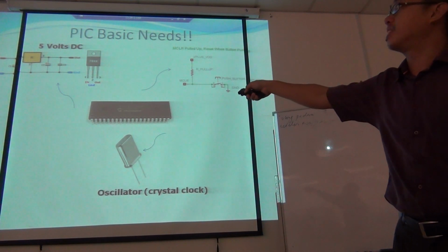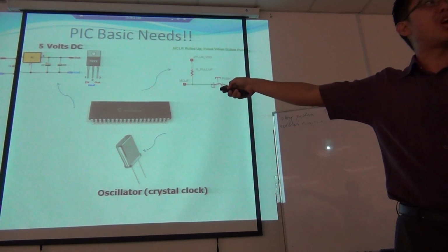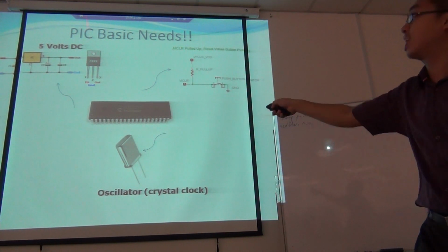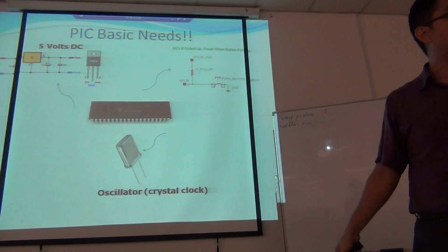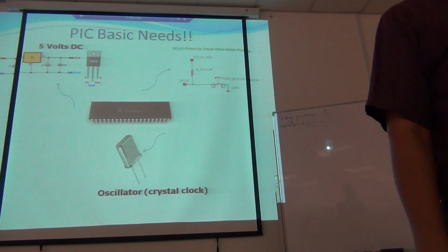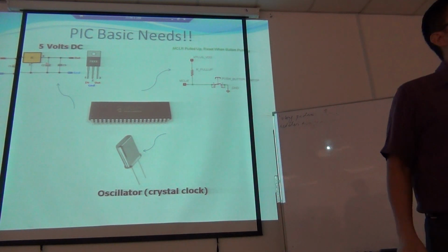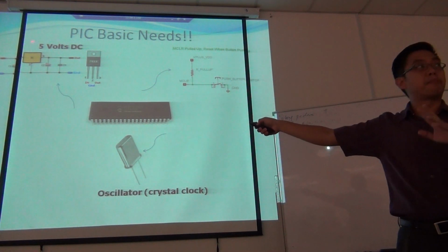So this IC is receiving around 12 to 24 volts. It will cut down to only 5 volts, and then supply the board. Okay, 7805. Alright, remember that. So the first one is the power supply.